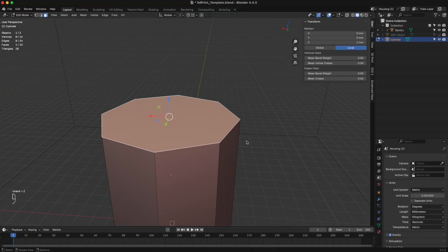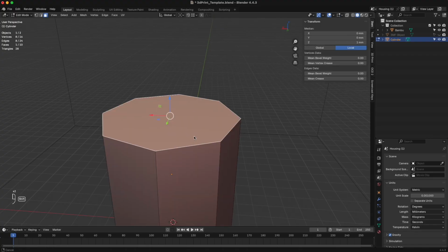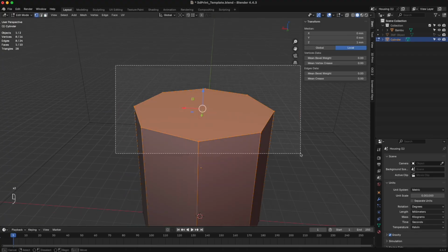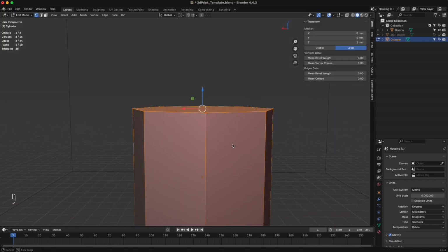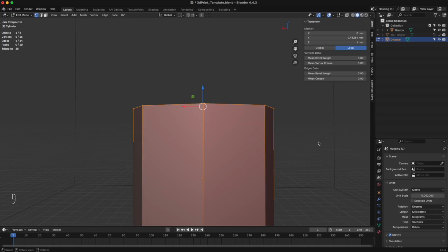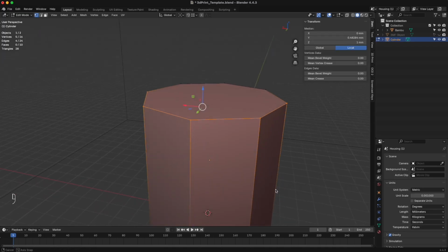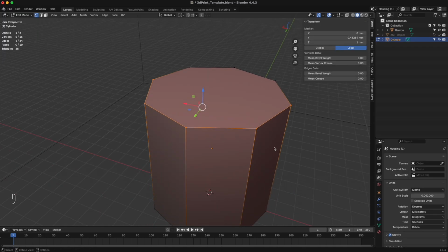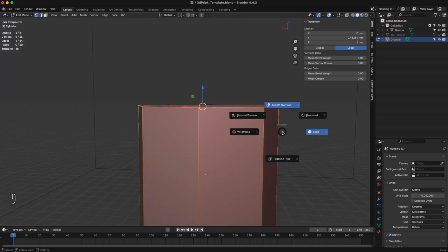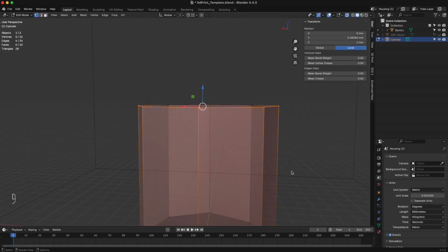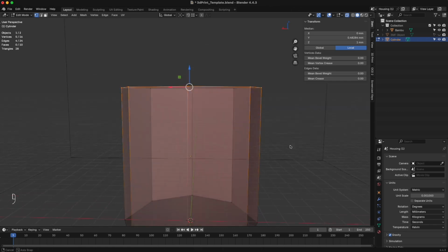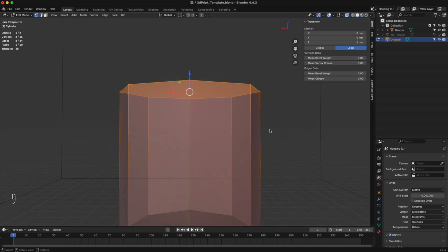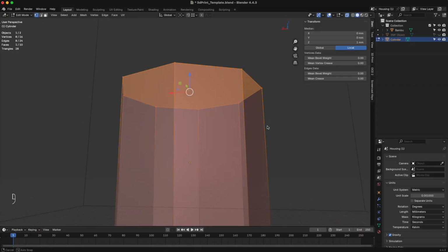So that's worth noting. Okay, so we're going to go into edit mode by hitting tab, hit the 1 key, or I could have just used the face that was there before, and I want to scale this. I'm going to show you something real quick. What if I wanted to get all the vertices, but this is the view I was at, and I zoomed up and notice I didn't get these back vertices. If I hit the Z key and I go into toggle X-ray, I can see now through it, and now I can grab all those vertices.